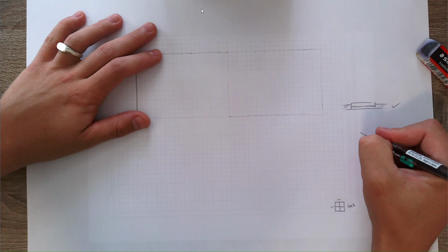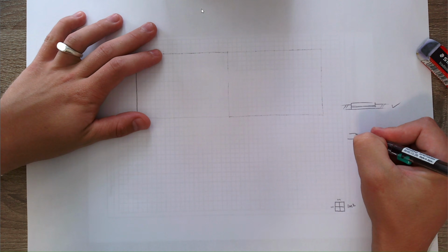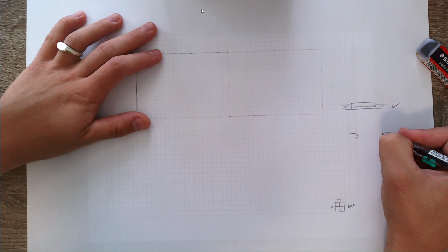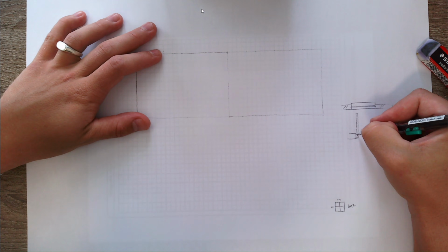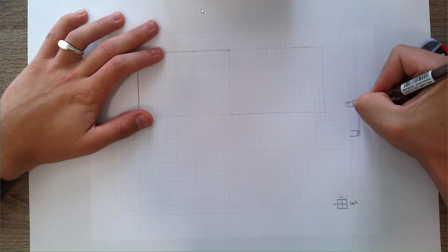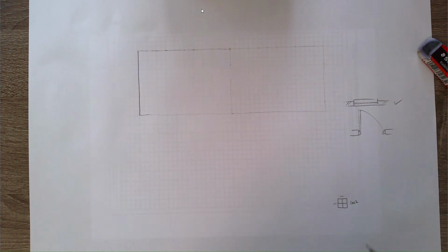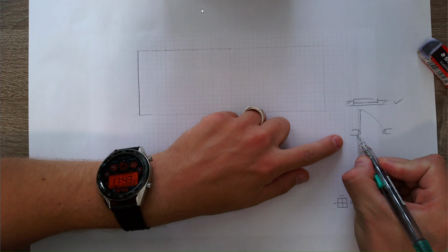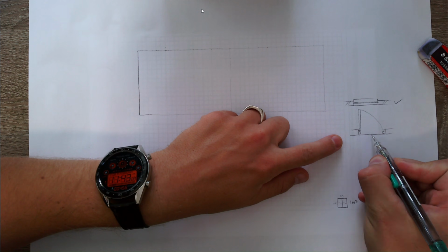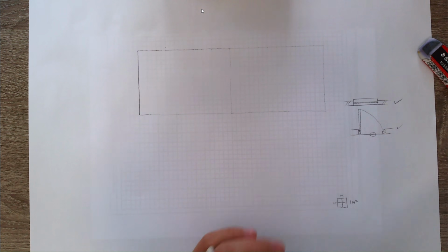When it comes to doors, you're going to have the walls. You can put in the door frame, put in the thickness of the door, and give the swing of the door as well. When you put a door in on an external wall, remember that you need to give that line there as well to show the step into the building. So that is the door, that is the window.